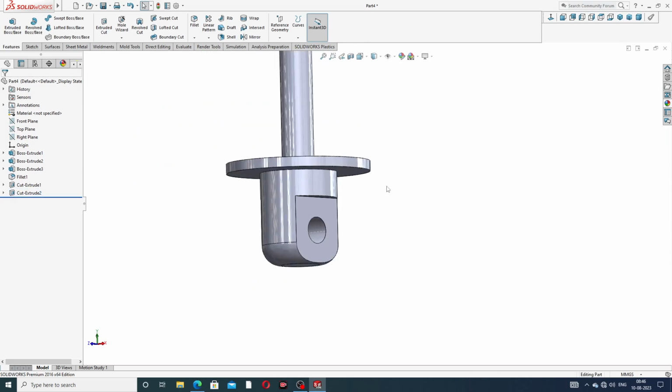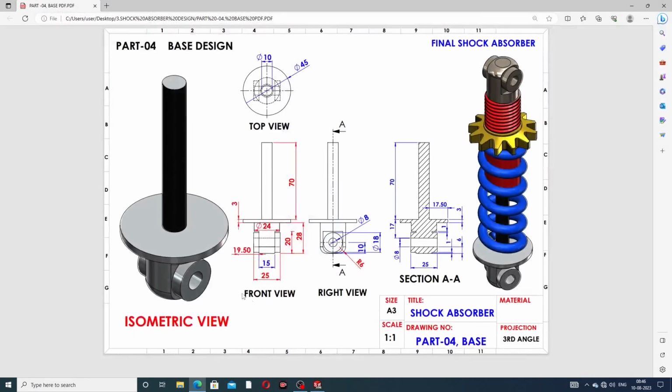Okay, and next is drawing this body. A circle is drawn here, 18 millimeter, and this thickness is 25 millimeter, mid plane. Okay, and this 25 millimeter is the same, and the 8 diameter, and this diameter is the same here. Okay, and this length is also the same, and this thickness is also perfect, and all is not mentioned here.